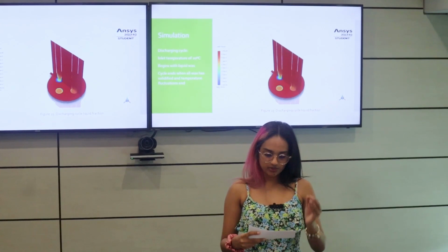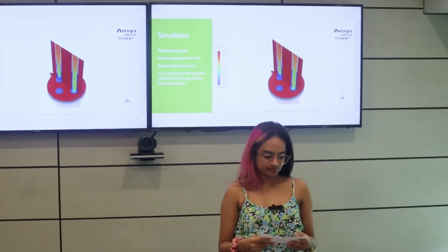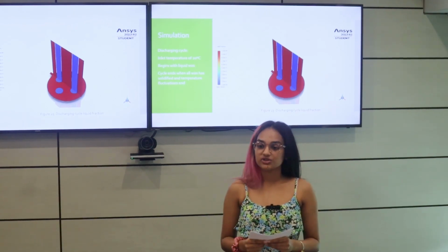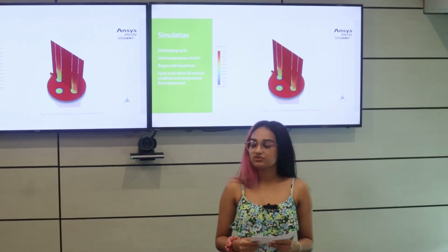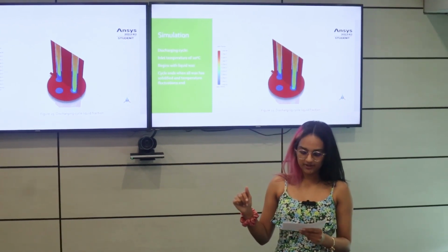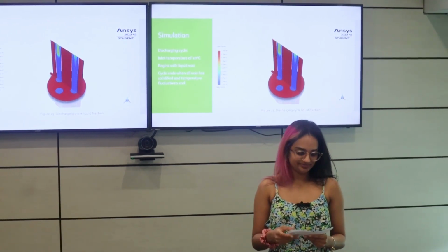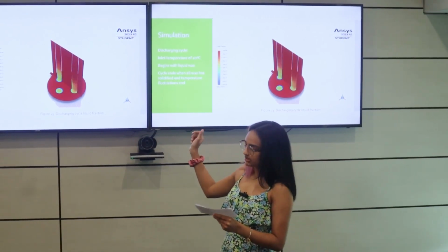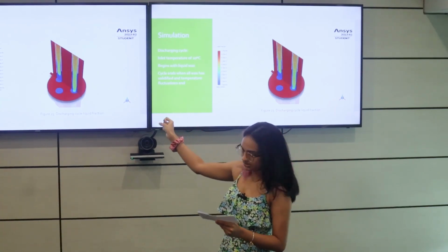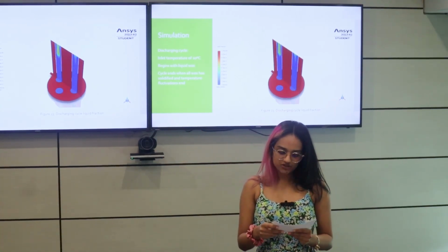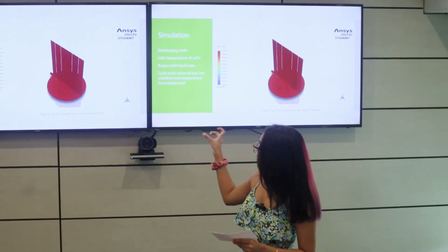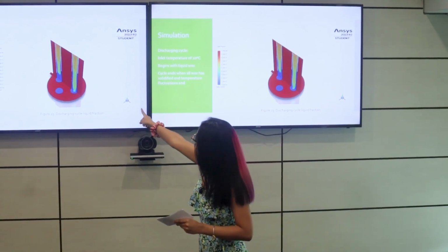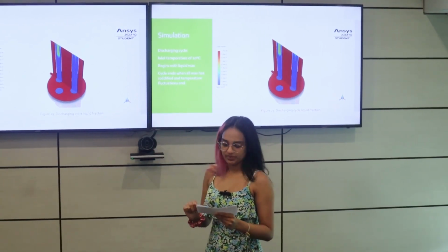Next is the discharging cycle, which is the opposite of the charging cycle. All components in the vessel begin at 70 degrees Celsius with an inlet temperature of 20 degrees Celsius. I have chosen to only show the liquid fraction here as it is the most interesting and relevant. As can be seen in this short video, the wax within the tubes slowly solidifies from the surface of the tubes inwards. This solidification process creates a solid wax barrier around the inside of the copper pipes, as can be seen here. You can see the blue slowly moves in.